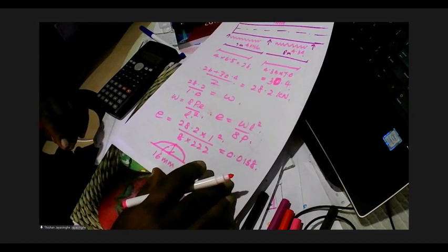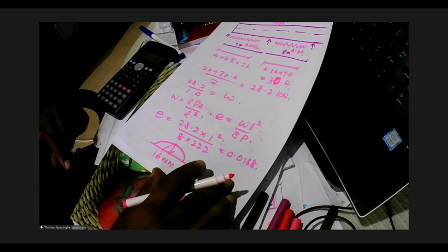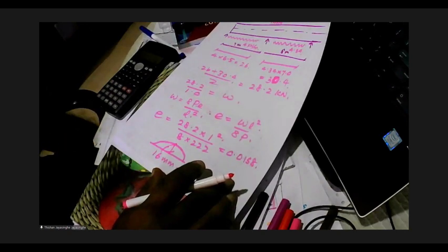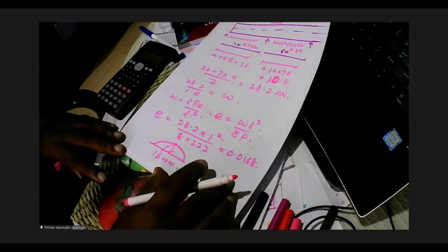So it has to go fairly flat in that region, and over 1 meter it has to reverse its direction. Because it's reversing its direction over 1 meter with a small eccentricity of 15.8, it can exert a big force onto the column strip, and that is the force that we expect from both sides.